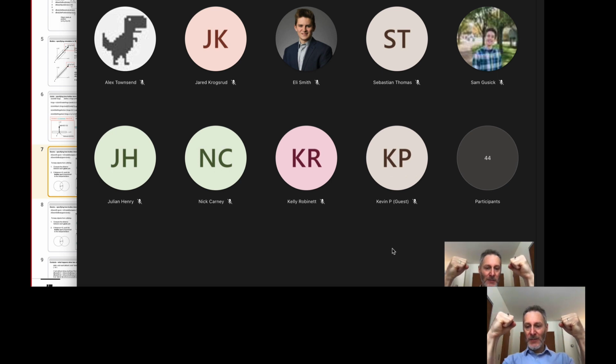Remember, at every time step in the simulation, their positions are changing, and depending on their velocity, at the next time step, they may interpenetrate with one another. The physics engine computes the amount of interpenetration and then applies forces pushing them apart. If we have objects that are moving at a low velocity, then at some point they're going to interpenetrate by a small amount and be pushed apart.